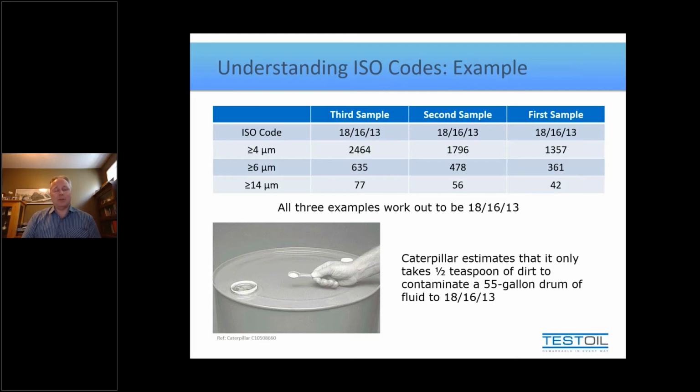So take 1/2 of a teaspoon and multiply it by 4, you end up with 2 teaspoons. It tells you there's approximately 2 teaspoons worth of material in every single drum of brand new fluid that has not been pre-filtered, just taken under standard delivery conditions. So it starts to paint a picture of just how much material is actually in a drum of oil. And if you look at the rest of the ISO code, compare 20, 19, 16 to 18, 16, 13, that's 3 codes higher on the last 2 categories. So 3 codes is double it, and double it 1 more time. That's 8 times dirtier. So to appreciate 8 times dirtier, that would be about 4 teaspoons.